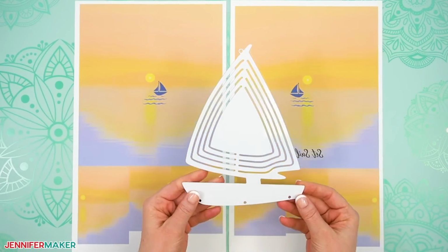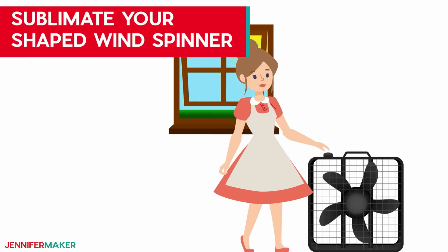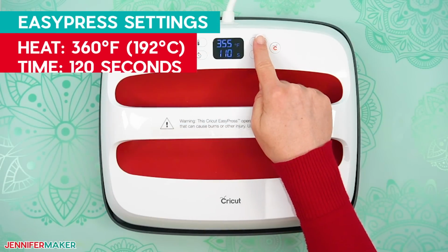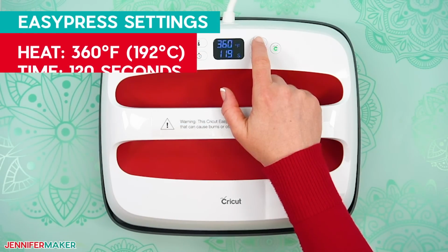Your images are ready to press. As with all sublimation projects, open a window and turn on a fan to improve your ventilation before beginning. Set the temperature of your Easy Press to 360 degrees Fahrenheit and the timer to 120 seconds.